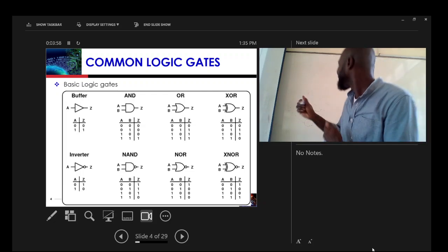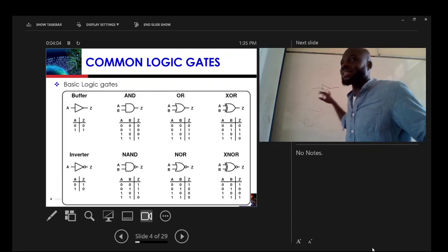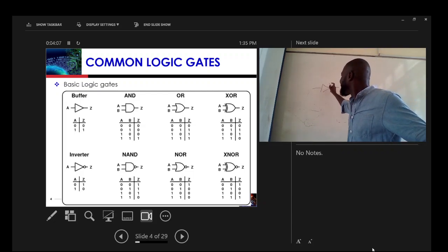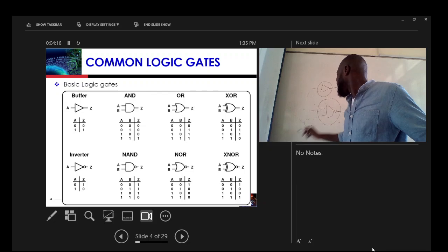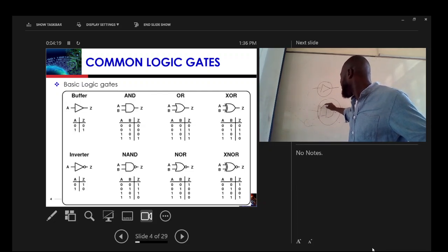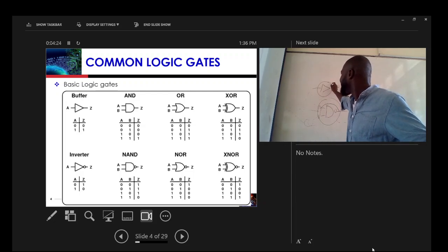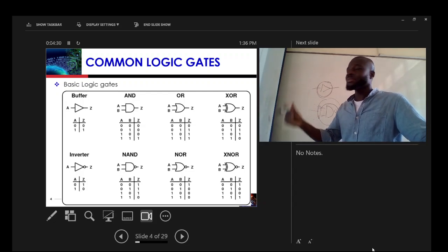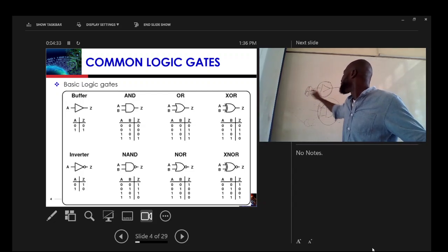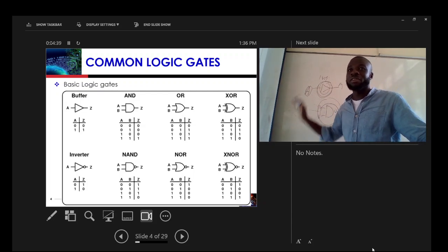So you see that this is just the buffer. It's passing the signal just through it, right? Each gate is made up of transistors, and once you are sending a signal from one end of the transistor to the other end, there's a kind of delay. So this gate just delays a signal by some amount. You give it an input, it delays the signal by probably 1 nanosecond, and then the output comes here. Very, very important circuit.